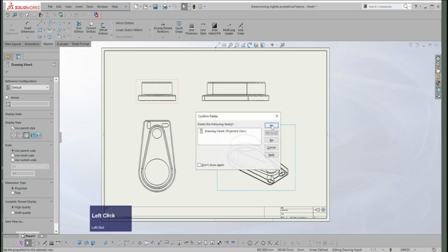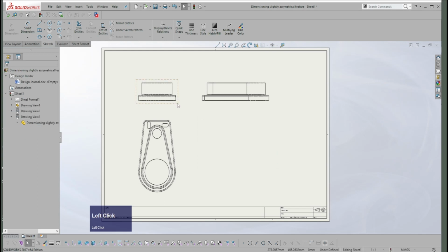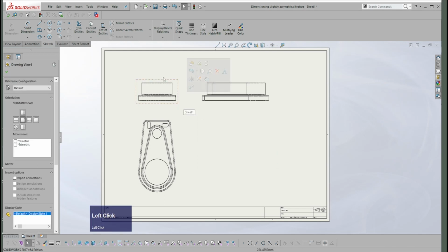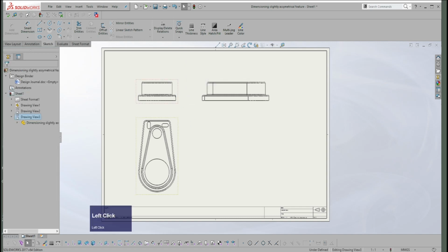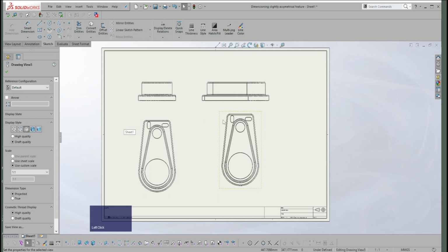So I'm going to delete this view. And the quickest way to recreate it is to just copy another view, another primary view. I'm just going to see if I can copy a secondary view and if that'll do it. So I've said Control-C. I'm going to say Control-V. And then you see now, since it's a secondary view, I can't change what the view looks like.